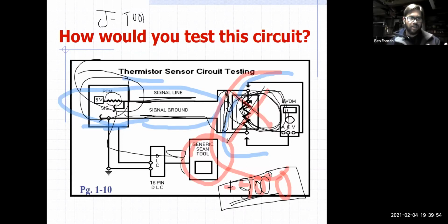And so, I used OBD2 generic data. And actually, in this scenario, I would use that and I would not use the factory tool. Why? Because this tool will lie to you doing this exact test. Okay. And remember, in OBD2 generic mode, it's not allowed to lie to you. So again, I just wanted to use this as an example.